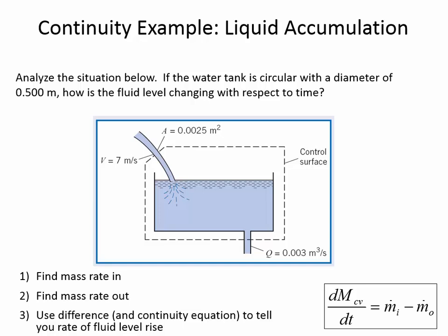It looks like this is actually an enclosed pipe. It's not like a free jet that's coming out. So it, not pictured, might be some sort of a flow regulation valve. But I'm just telling you that one variation of this type of problem is asking what would be the height of the water when it reaches equilibrium. Because in that kind of a problem, you'd be saying, assume the flow in and the flow out are equal. So you'd need to know what velocity is going to give you the mass flow rate out that is equal to the mass flow rate in.